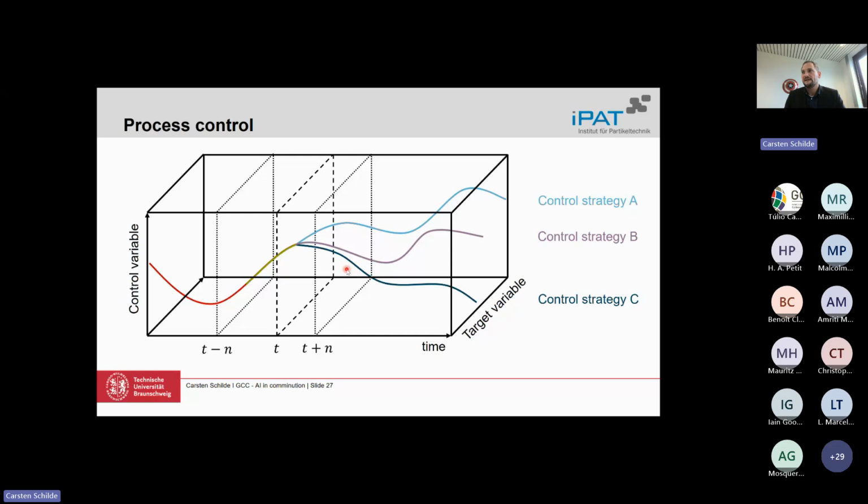What does it mean? We take a short step in the past, apply the model to our grinding process, so make a fit. Then the model predicts, based on that fit, possible future steps if we now make a change. So that means not only to predict a certain point in 1 minute, but the whole evolution, how the values evolve in the future.